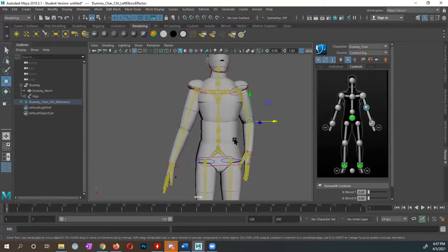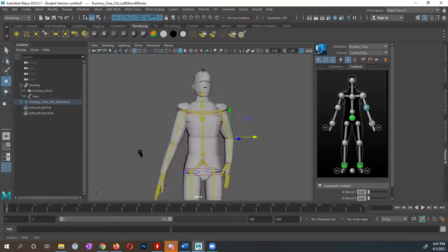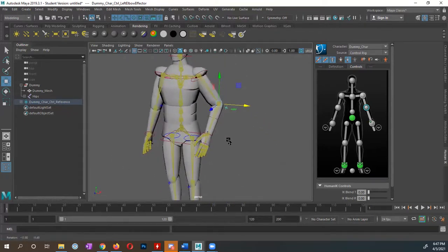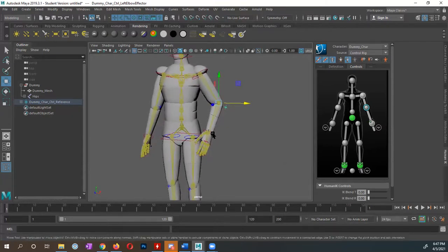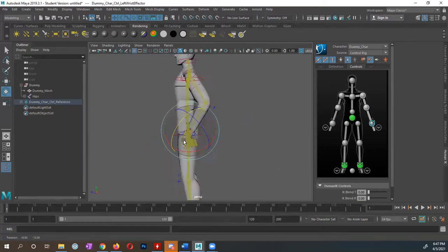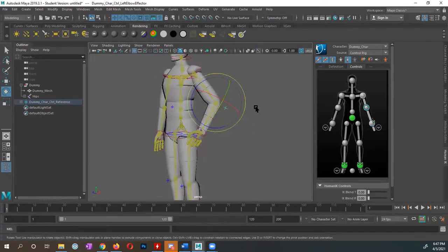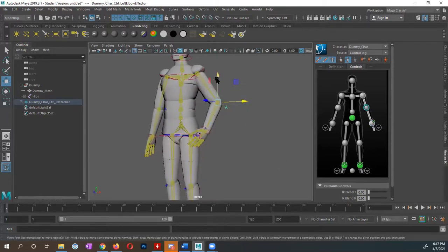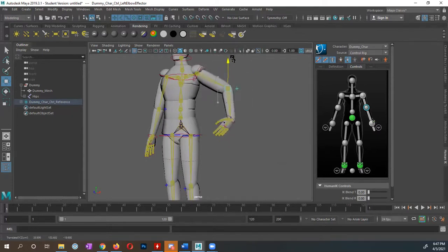Now the other option that we also have is we could pin the rotation. Let me try to situate this one where, let's see, I'll use this arm again. This time I'm gonna unpin the translate, but now what I want to do is pin the rotation. So I'm gonna switch to my rotate tool where I have the hand right here. And if I select this one, switch to my move tool, you see how the hand is still pointing downward? It's because the rotation is pinned.